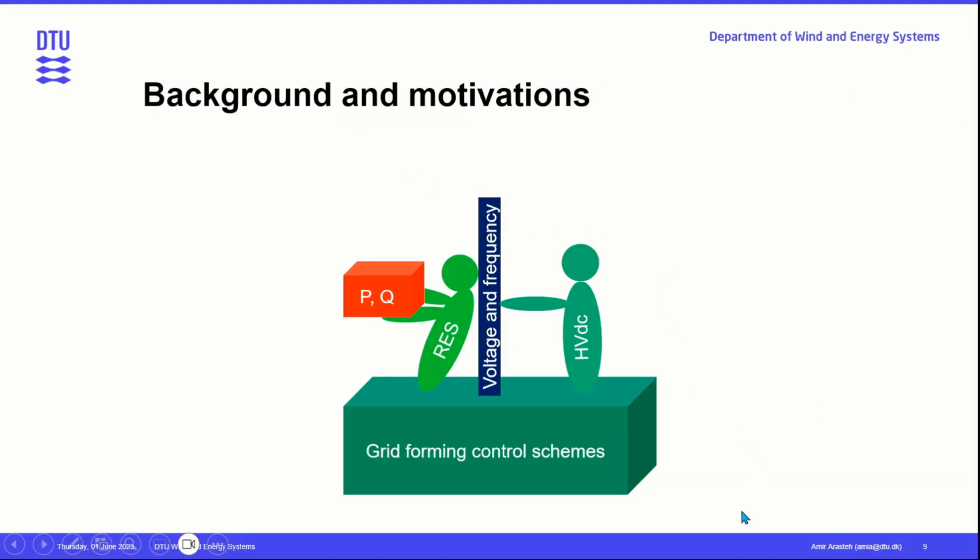So the other wind turbines are able to control their active and reactive power by relying on the provided voltage and frequency by the HVdc link. Yes, so it's important to know that this is a special case, and that is why we actually can dictate the frequency in this case, because there is no other synchronous generator in the offshore system, and we can fix the frequency.